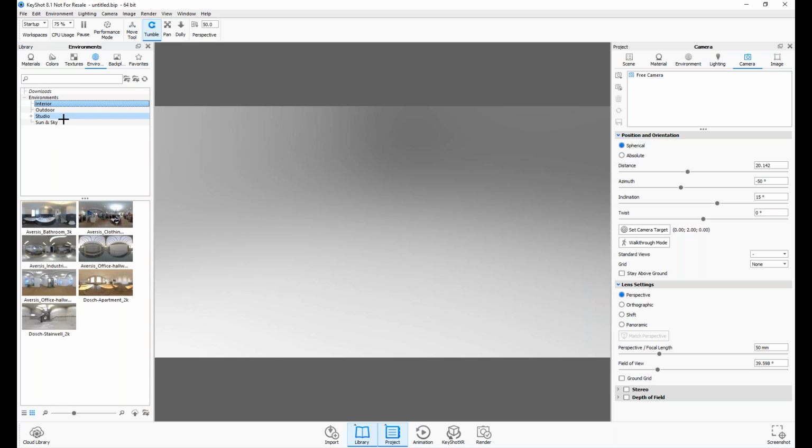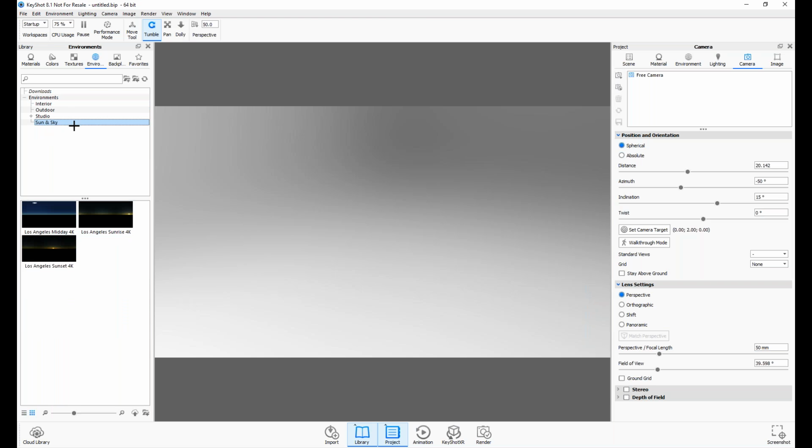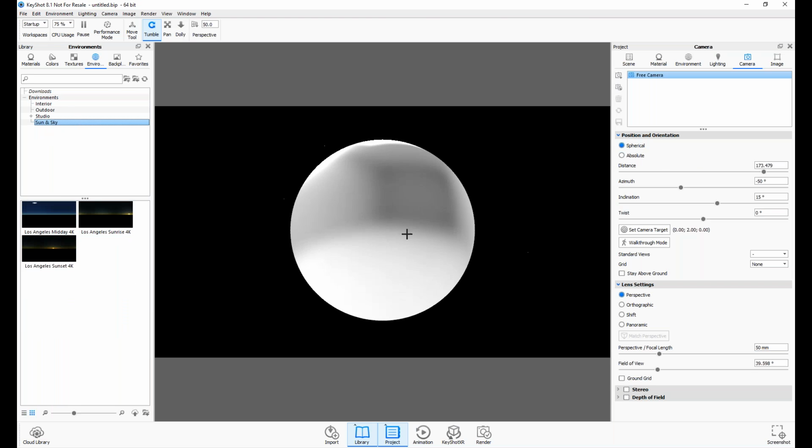This includes our default HDRIs. And HDRIs are the sphere in which our model will reside. So if I zoom out here, you can see a sphere currently empty. I haven't added my model yet, but this HDRI environment will determine that default lighting that is taking place just from that exterior surface. You can always add models within the environment and then apply lights as materials to those models to have more dynamic lighting, but the HDRI environment does allow you to very quickly have high quality lighting in a time-sensitive fashion.